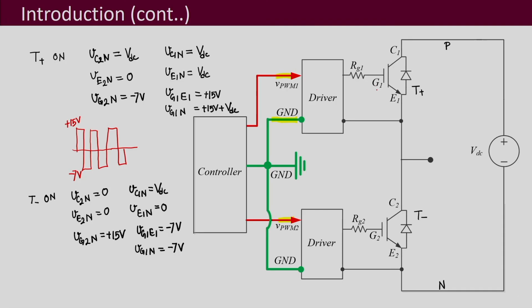Then one more thing that you should note down is that this gate emitter region has its own requirement. Now, here I have taken plus 15, minus 7 volt. Always it may not be plus 15, minus 7 volt; different voltages may be required to push it into the ohmic region or the saturation region.